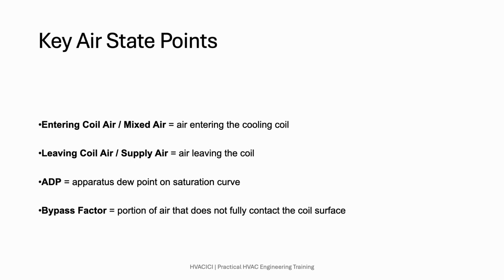The key points are entering coil air, leaving coil air, and ADP. The entering air is often mixed air. The leaving air is the air leaving the cooling coil. ADP is located on the saturation curve and represents the effective coil surface condition.